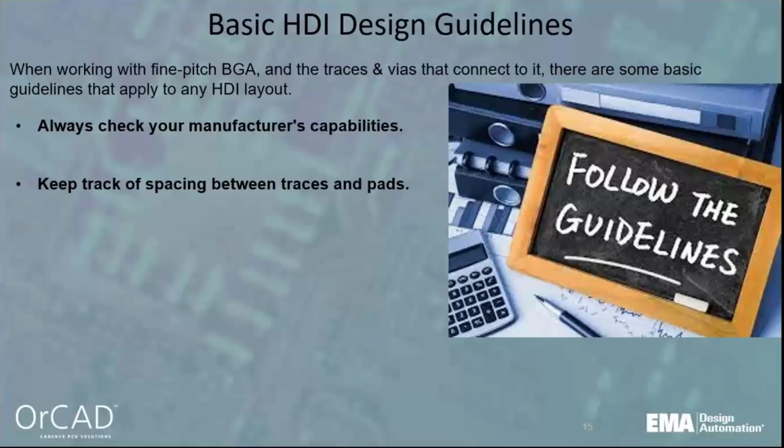Keeping track of spacing between traces and pads is going to be very important. So a constraint manager is going to be very important to you while you're designing. Setting up those constraints with your engineer and your manufacturing are going to be very important, and that's something that we can help you with in the Allegro tool.